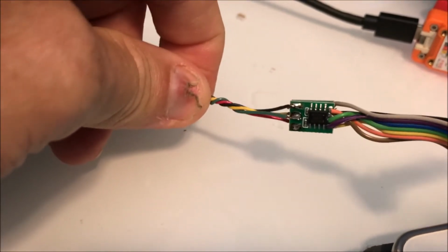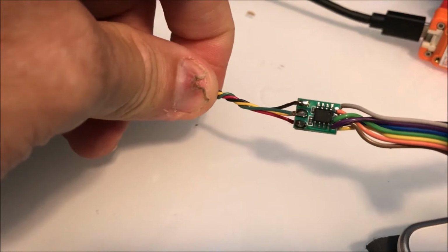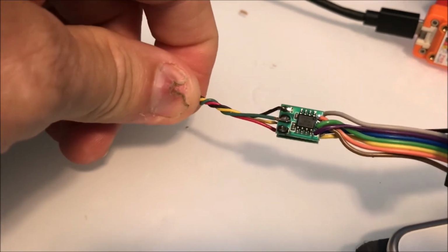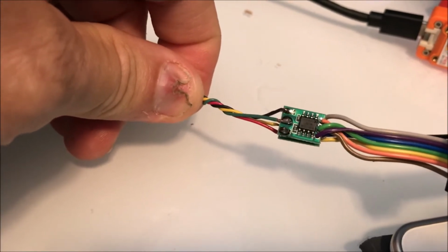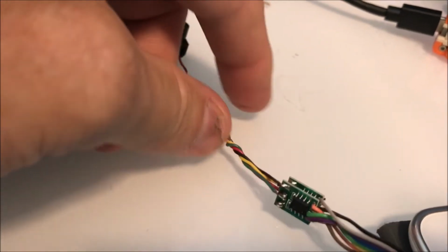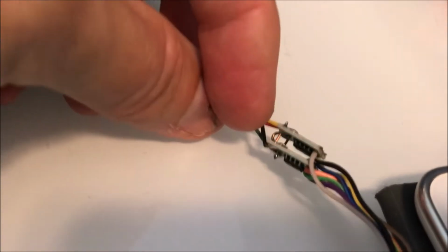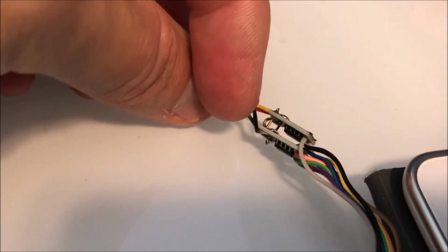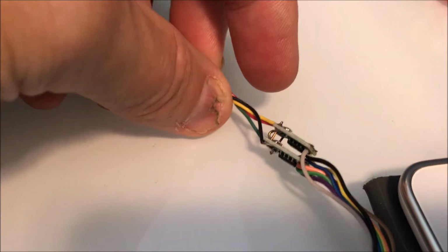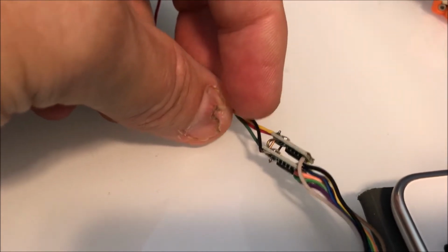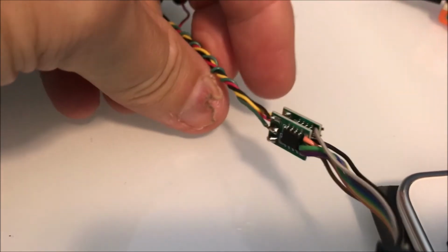because each little board has an output. Let's start off with the input: it's 5 volts, ground, and then signal in, and then actually on the back of the board is an out. You can see there's a tiny little gold pin there. It goes from the out of that board to the in of the next board, and the 5 volts and ground are fed through.